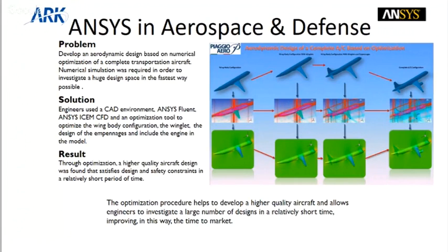Most of the time you can see it on a lower portion of the wing. If it is an Airbus 380, then you can see that there are two engines assembled at each wing. So what should be my position? I will go for distance. I will manually take different distances and optimize the strength: if I put my engine at some particular position, it should not affect the strength of my aircraft.